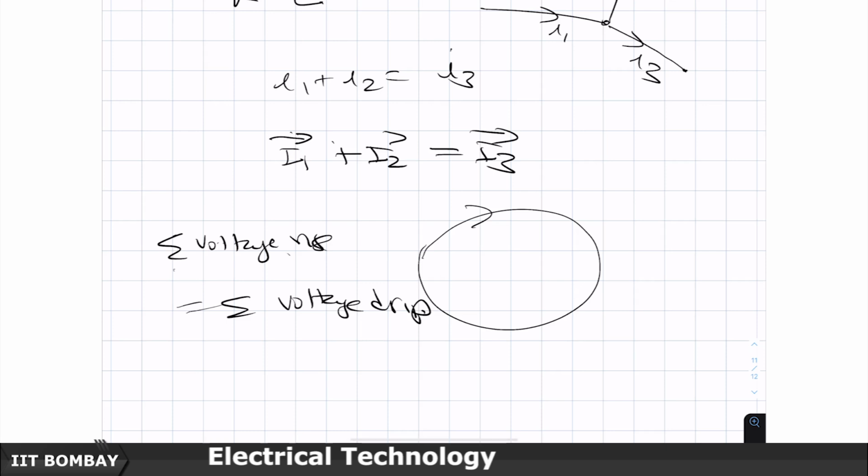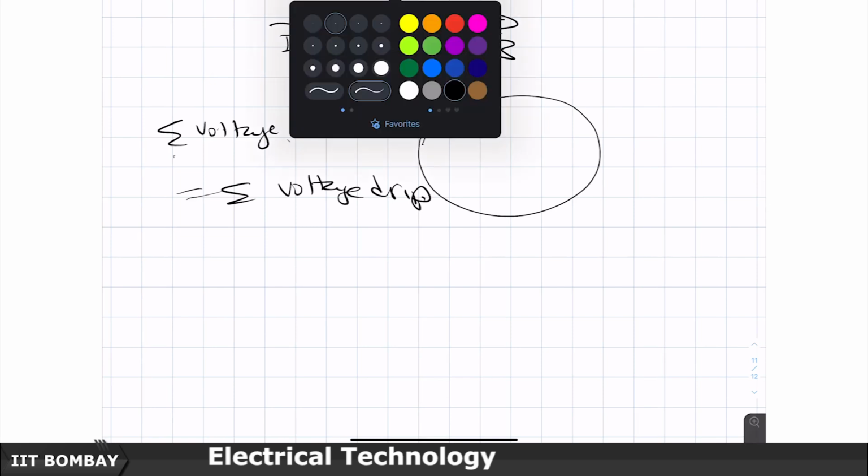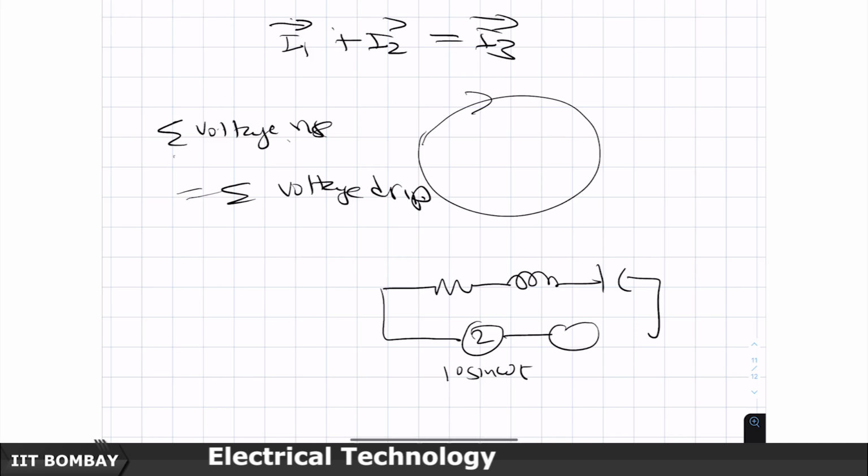Now, suppose in my RLC circuit I had connected one voltage source, say 10 sine of omega t, and another voltage source, let us say 20 cos of omega t. I can do a phasor analysis because I can apply superposition, find the response for the current with 10 sin omega t, and then with the other. Both of them will be two phasors at the same frequency omega.